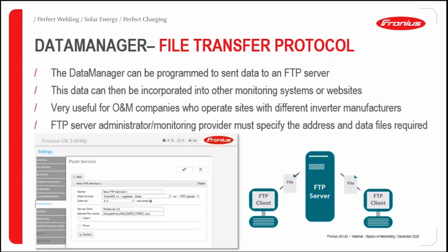It means you can see all the data in one place for all those different manufacturers. The FTP server administration or monitoring company will need to provide you with the server address and also the specific data that should be sent from the inverter. This can then be input into the data manager settings so that the data is pushed to the right server and providing the data that is required by the monitoring provider.